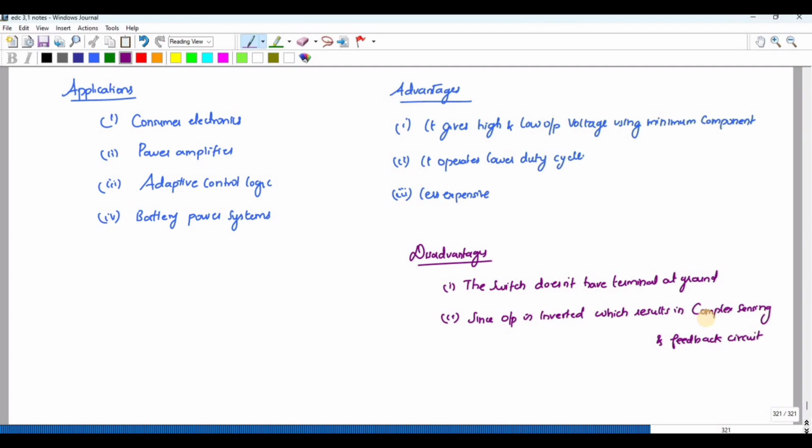Next, high gain cannot be achieved with this connection type as the efficiency is poor, and the input current and the charging current of the output capacitor here are discontinuous.